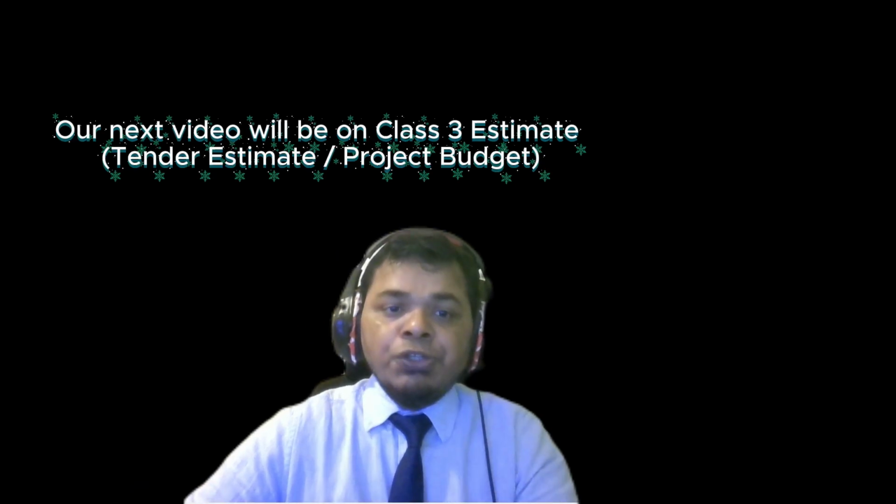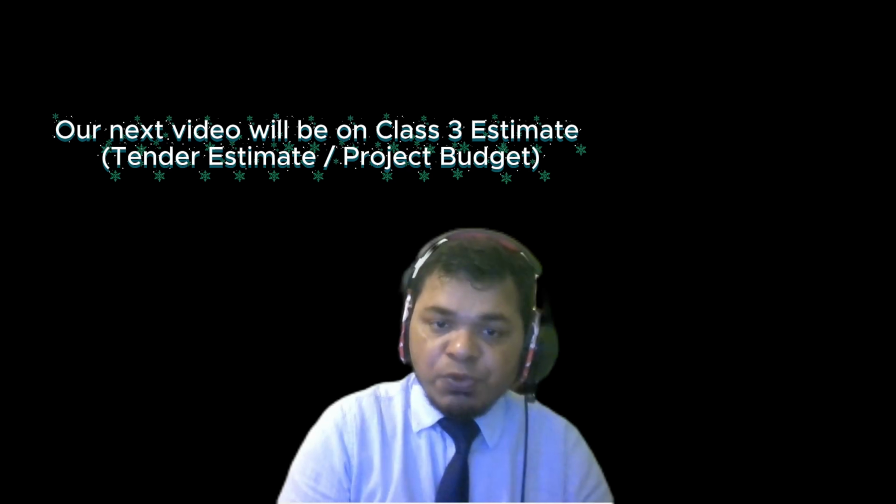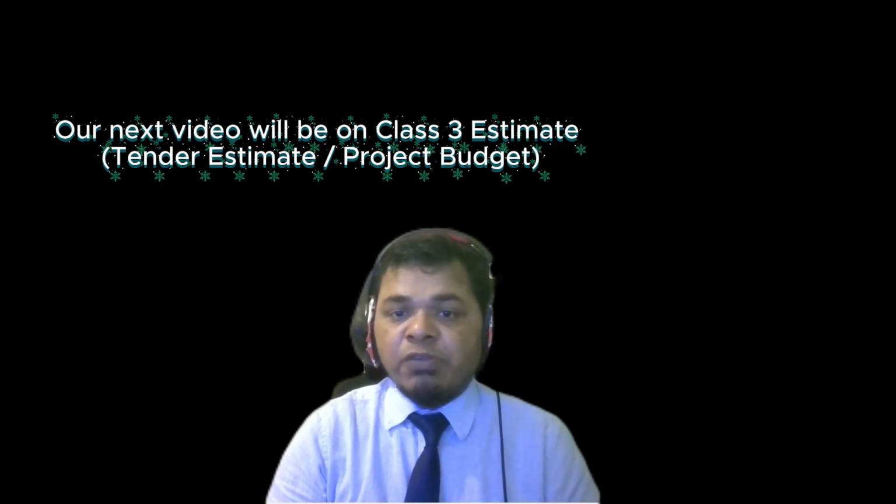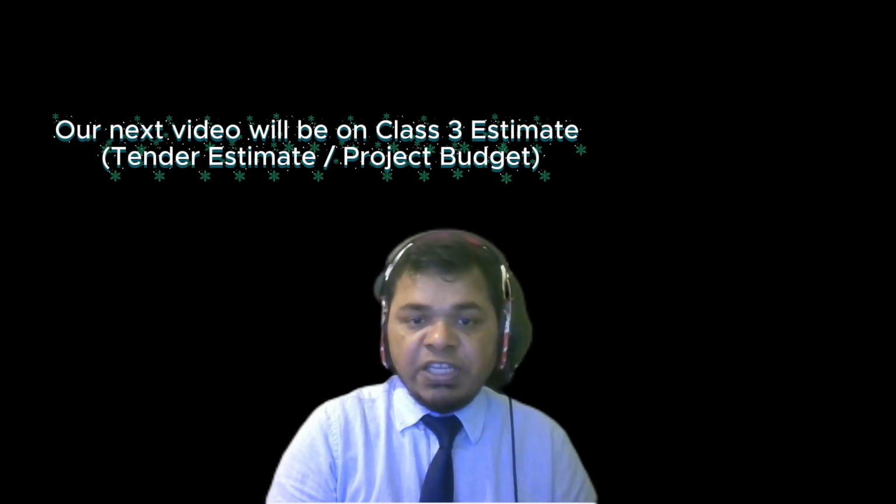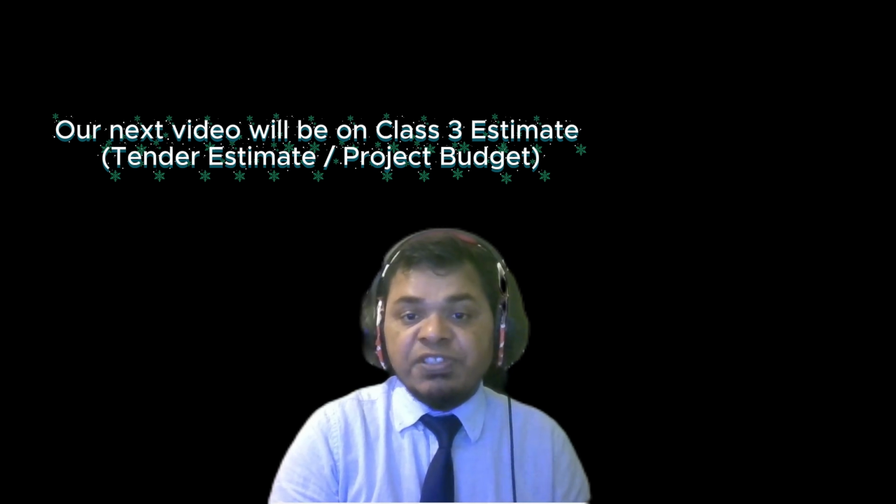Data from very large projects, say 20 billion, may not be appropriate for estimating a small 5 million project, even if it is a similar facility, because unit costs behave differently at different scales. Large projects often reduce unit cost, while a small project may have higher cost per unit. So when estimating, it's important to analyze available data carefully, make reasonable assumptions, and adjust for differences in type, scale, and quality. This approach helps produce a more realistic estimate.